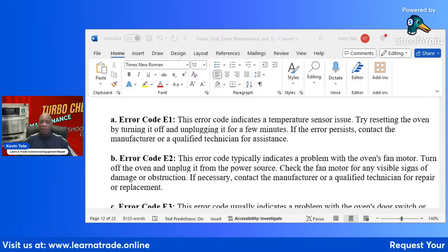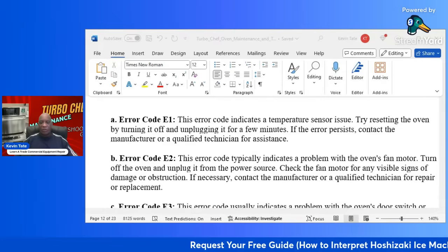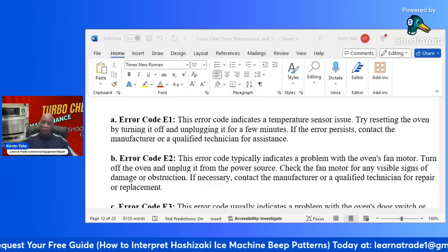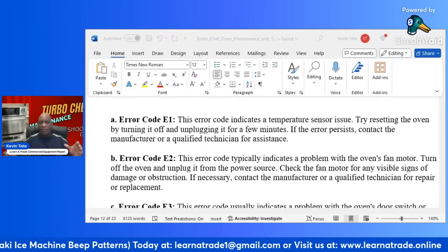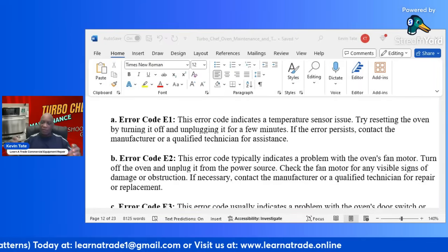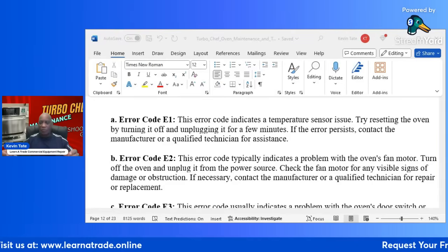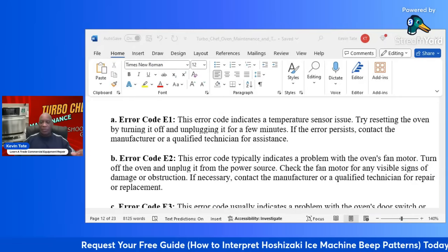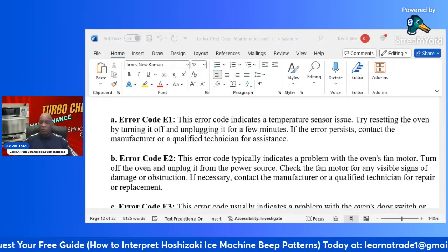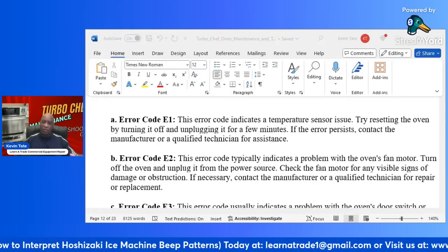Another thing that happens with those blowers are the fins. The fins have a ring that goes around them that binds them together and holds them all together. If that binder is off a little, off of one of the fins or a couple of the fins, then it's not going to turn right. It's not going to get the proper rotation for blowing, and then the board senses that there is a slow heat gain, so then it'll go into the error.